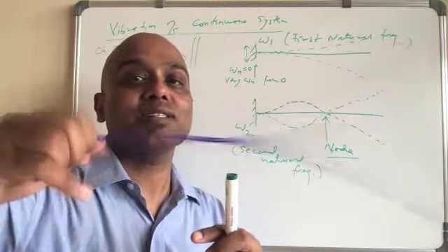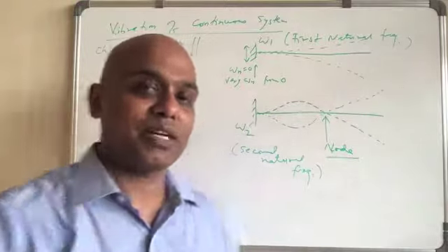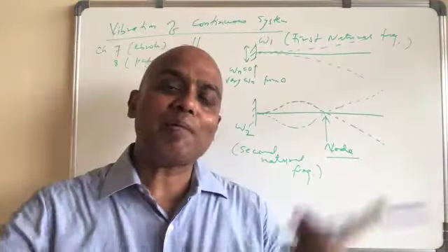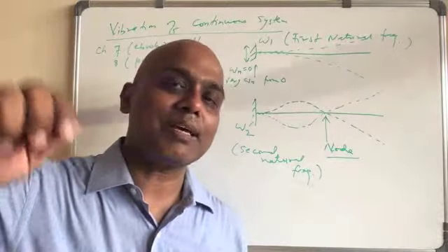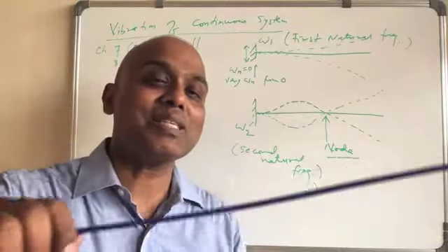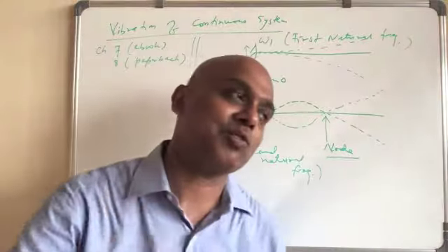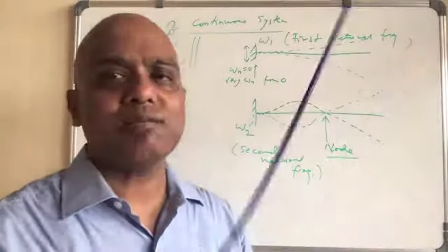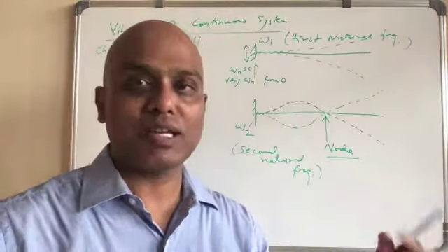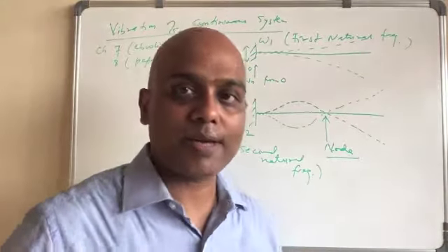So this is the second mode of vibration. Similarly, if you have a machine, you can increase the frequency of the base excitation further and you will see 2 nodes, and so on. Basically, if you have a flexible stick like this one, you can do the experiment yourself to see that.